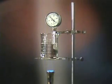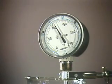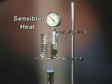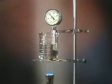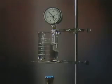We'll use this beaker of water to demonstrate a phase change and to identify a couple of types of heat transfer. As the water is heated, heat is transferred to the water, and its temperature increases. The heat that is transferred when there is a temperature change is called sensible heat. In other words, sensible heat transfer is heat transfer that can be sensed by thermometers and other instruments as a change in temperature.